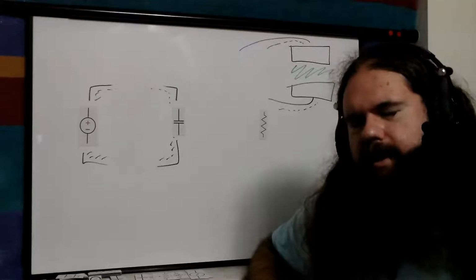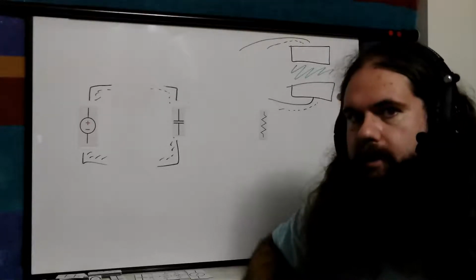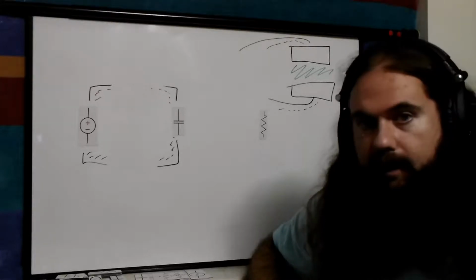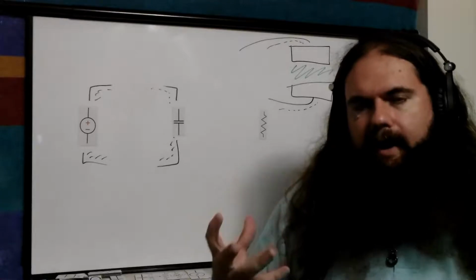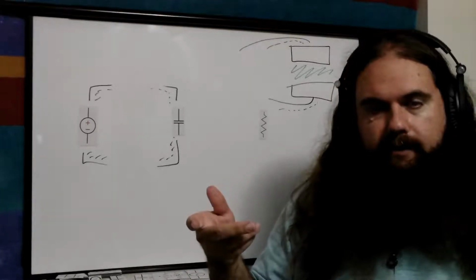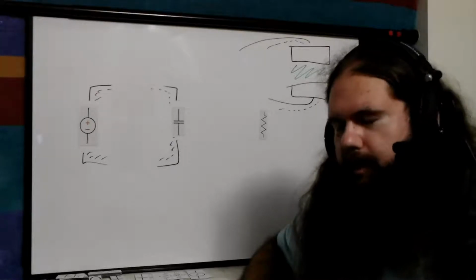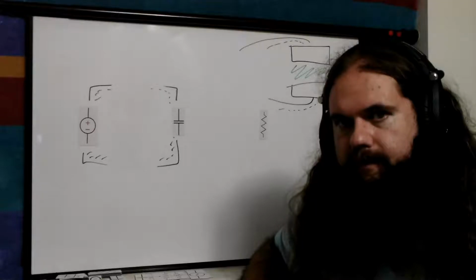So this is why it's dangerous. You might see electrostatic discharge or other electric shock warnings when opening a device that's not plugged in. When you unplug it, there are still capacitors, especially if what you're unplugging is a power supply, like a power supply for a computer or a wall wart. Those will have capacitors in there for smoothing out the voltage, and those capacitors can stay charged. And if you touch them, woe be unto you.